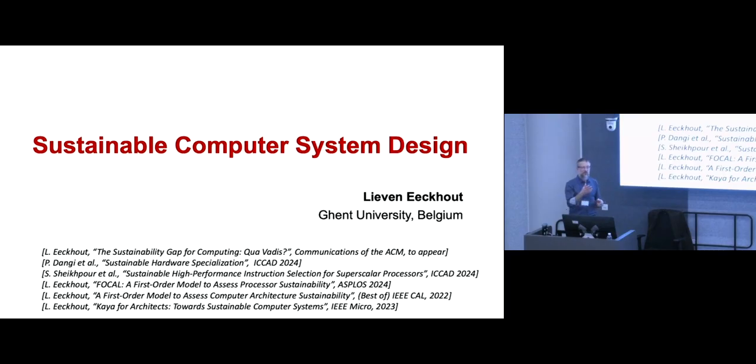But it turns out from several studies that we're not using tens of accelerators at the same time. It would also be impossible to do so because of dark silicon. So what you typically see in applications is 2, 3, maybe 4 DSAs being used at the same time. So if you want to replace those with a CGRA or an FPGA, the reconfigurable fabric would need to be big enough to accommodate all those accelerators, such that you can have them all operational at the same point in time. You see? Okay, so all the ones that you would typically need at the same time, but not all the ones you might ever need.